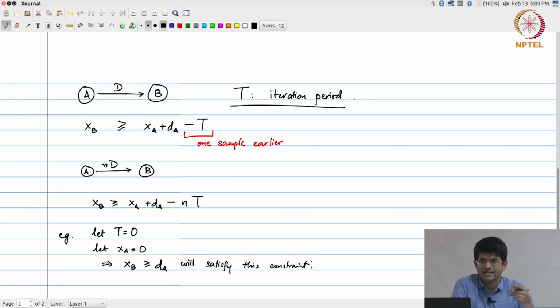In practice, those xa, xb, etc. will probably be some time instant, some clock cycle or something else, which is determined by some finite state machine controller, which says, okay, at this time instant, let this particular block start functioning. Okay. Or if you are talking about a fully combinational circuit, then there may not be a finite state machine controller, it is just going to be determined by, as and when one unit finishes, the next unit consumes its data and then starts executing, generates output, etc. Okay. That goes into a so called self-timed mode of operation.